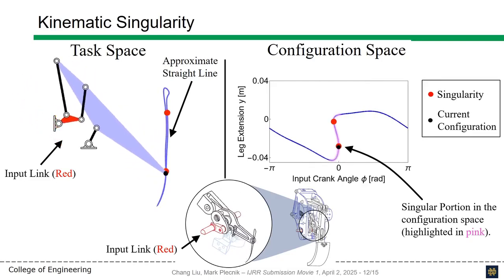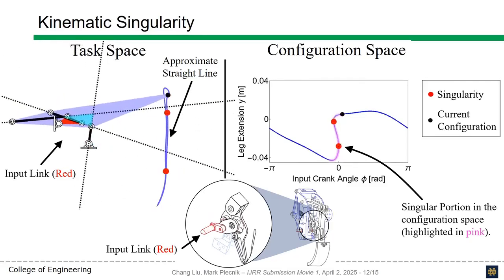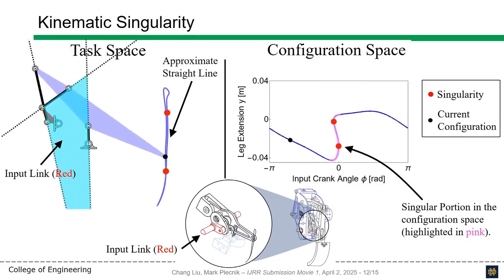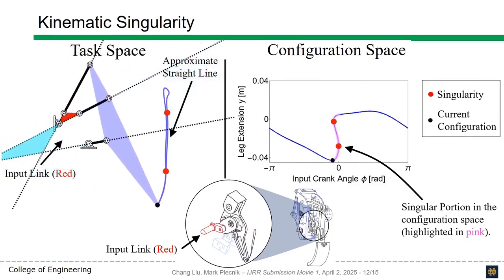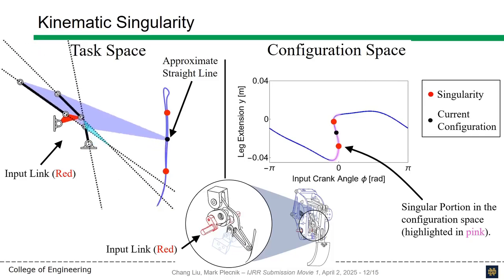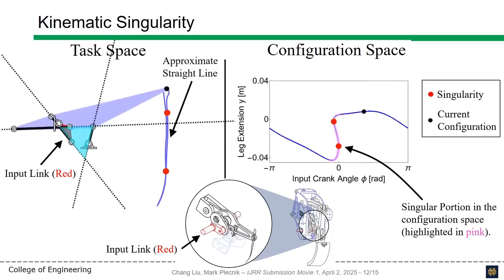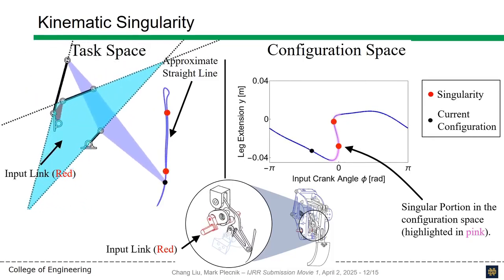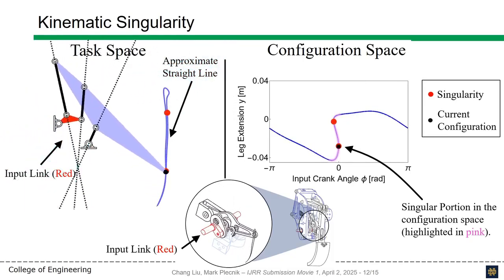Upon entering the near singular region, series elastic torque has no authority over the leg motion, meaning once it arrives, it comes to a stop, which is used to set the leg at its ready position while auto contact. Despite the leg not moving, the motor will continue to move, as the two are coupled by a spring, enabling auto contact spring charging.